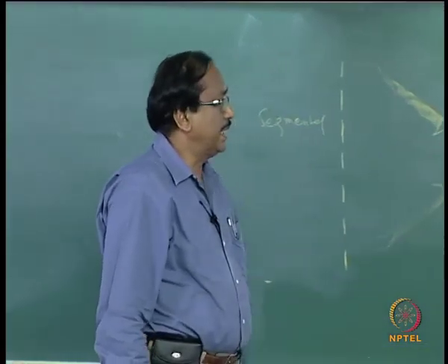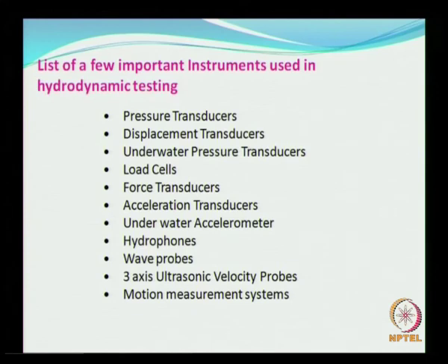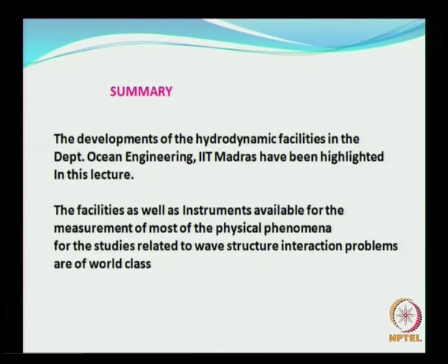Apart from the hydrodynamic testing facilities, to enable all the tests we need a host of equipment. I have listed a few of them: pressure sensors, displacement transducers, underwater pressure sensors, load cells, force transducers, accelerometers, then underwater accelerometers, hydrophones, wave gauges, velocity probes, motion measurement systems, and the list goes on. I have just listed a few.